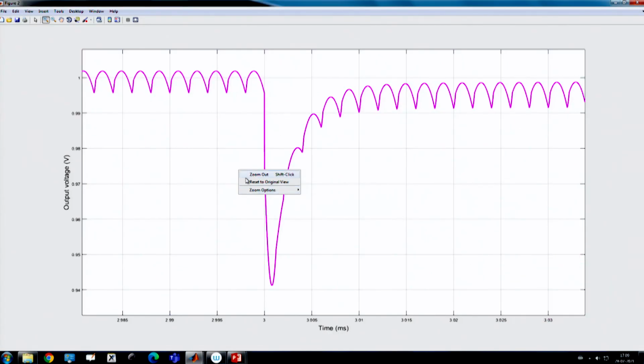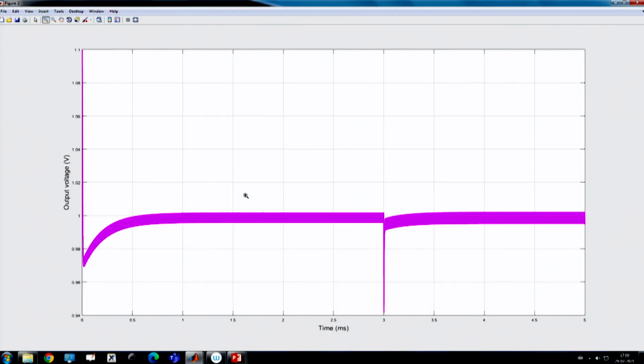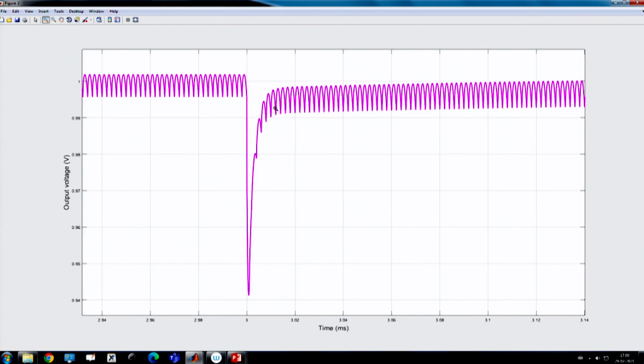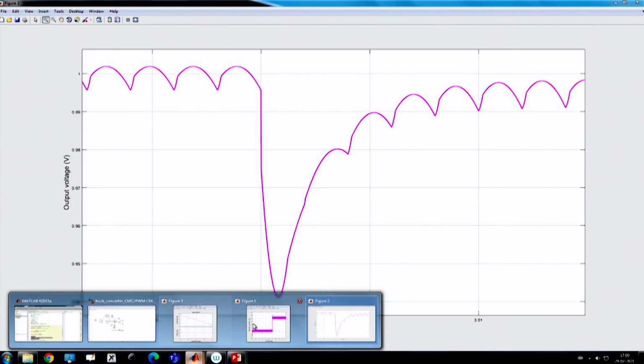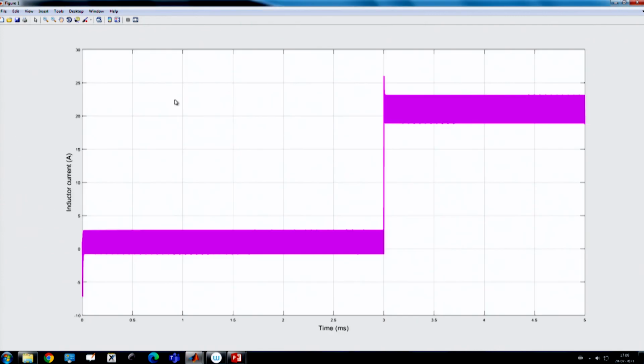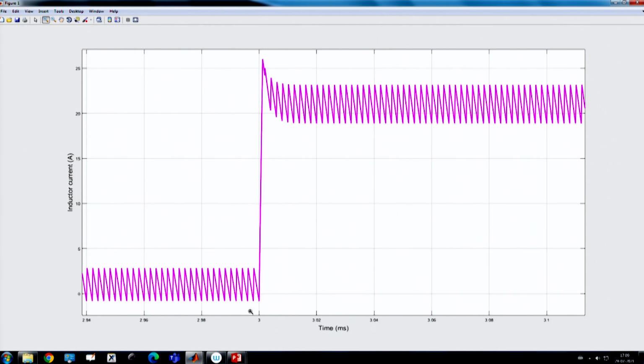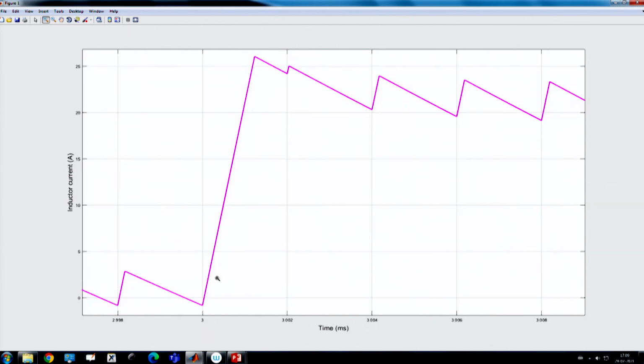That means, if you look very closely, except for this, because this is due to the finite slew rate of the inductor and capacitor, because inductor current is rising, it cannot reach immediately. If you go back here, as I said, it takes time, right, inductor takes time, it will slew up, and if you reduce the inductor value smaller and smaller, then this will become smaller and smaller.